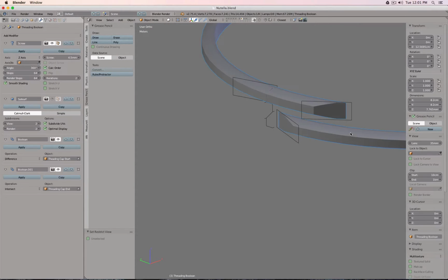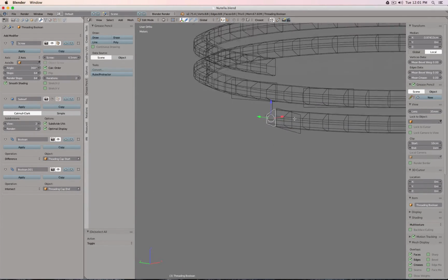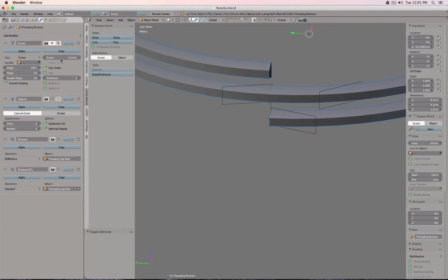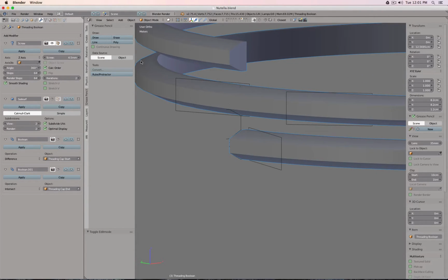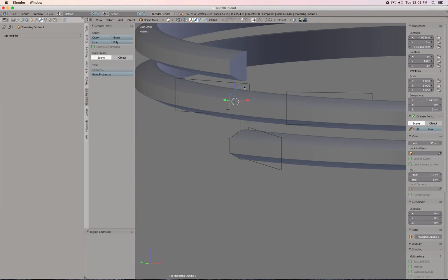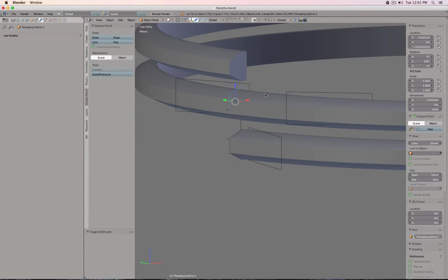And then I have here just this cross section. And it actually uses the screw command. You see, instead of one iteration, it does 2 iterations. And 4.5, that actually helped, or I came up with this number by aligning my screw value till it perfectly matched, for example, this upper profile.